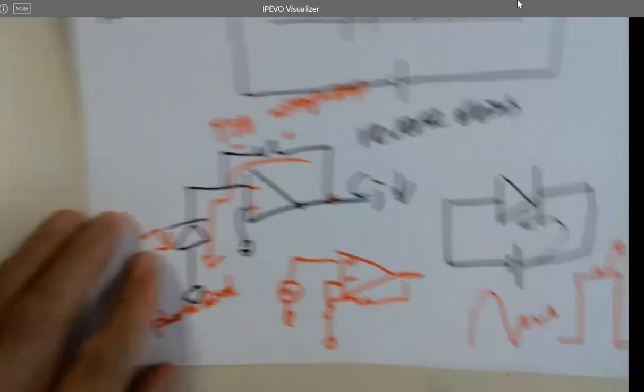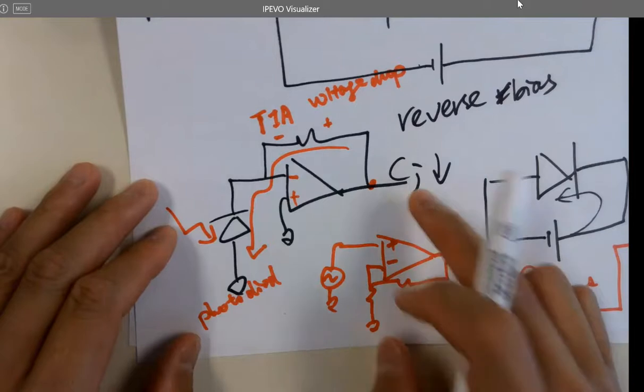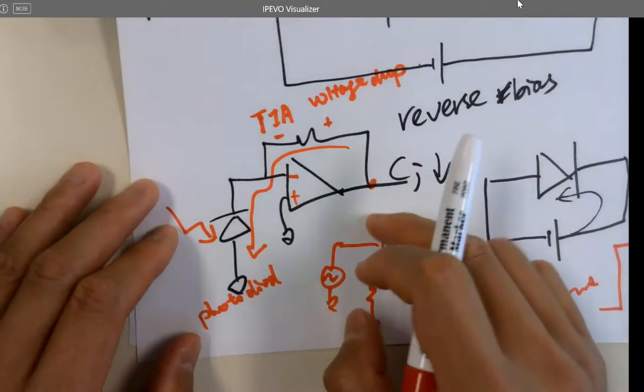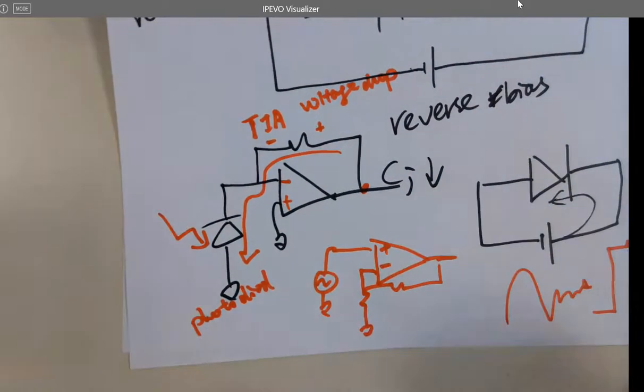That's why whenever you can, just convert into voltage as soon as you can before getting too much noise in there. And then you can digitize it with ADCs, and so you got digital signals and interface with the computer, with microcontroller, whatever. And after that, for the communication in between computers, in between digital chips, do you still need to DAC it, or just use a standard digital communication protocol? Yeah, just digital. And you want to use the least number of pins.